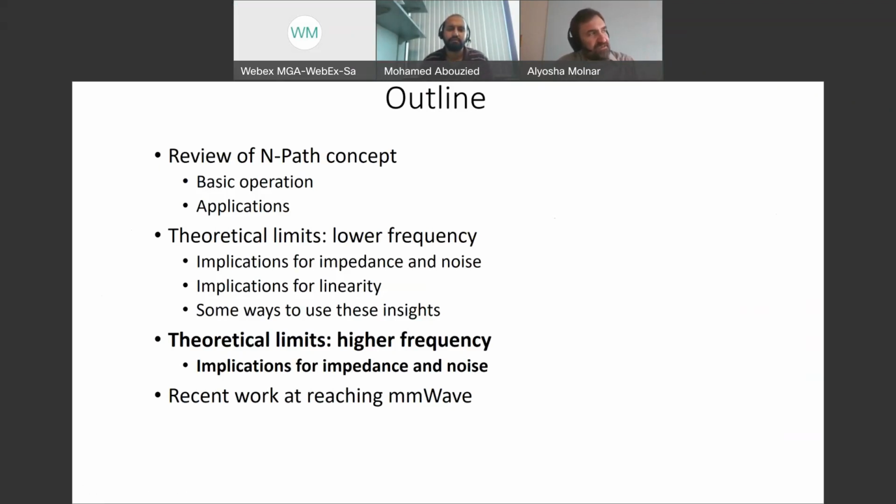People recently have been looking at designs, including us actually, where we put a bandpass filter on the output rather than a low-pass filter, and that can work. You can do IF systems that way, but the restriction seems to be that the bandpass filter's bandwidth still be narrow relative to the RF, like the clocking, the LO frequency. So the key thing is that you have memory from cycle to cycle. That can be a low-pass memory, or it could be a resonant bandpass memory, but that seems to be really important. Thanks.